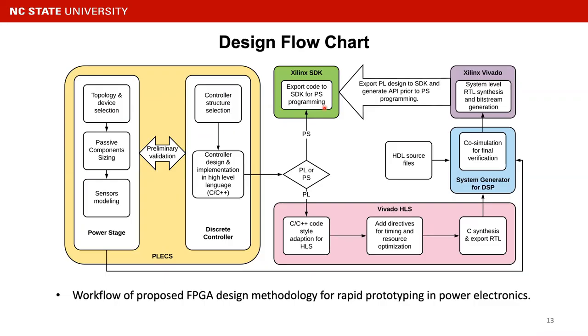Basically, we can directly copy and paste them into the Xilinx SDK because the ARM core is programmed with C language. However, if we want to implement some algorithm on the PL side, the process is slightly more complicated. To make life easier, we selected Vivado high-level synthesis because it can help us convert our C code into the RTL design.